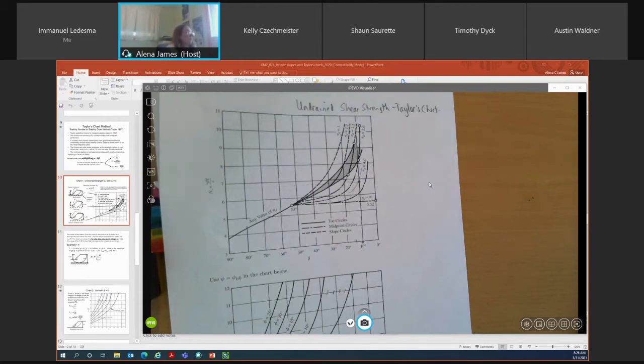I guess you could back calculate what your cohesion would be as long as you know what your height is, but you need height for both NS and for ND. So the only other unknown you could have would be undrained shear strength. So you could back calculate undrained shear strength, but you can't back calculate height. All right.